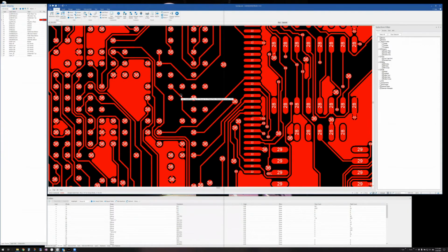The reason that we did make them different colors 20 years ago, actually it was about 25 years ago, is that a lot of the CAD systems would draw things like these ovals. PADS is notorious for drawing these ovals right here. And if you're going to run any kind of analysis on the design, you want them to be flashes, not draws. So we have a utility called draw to flash, and you would have to run that a lot.